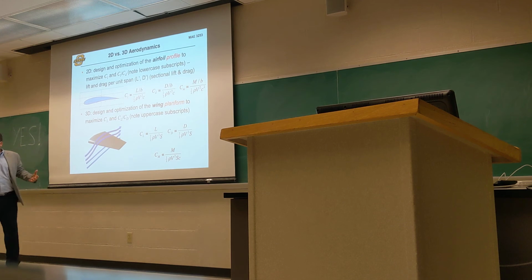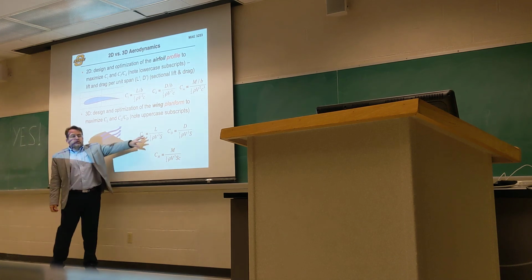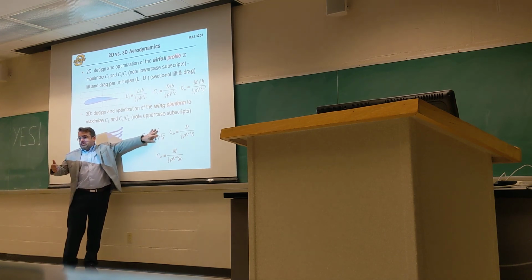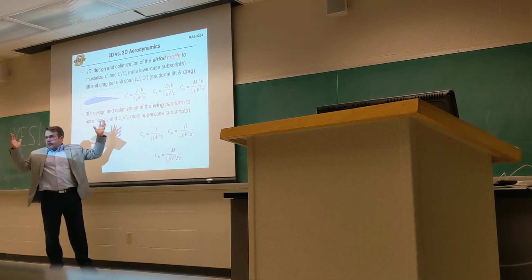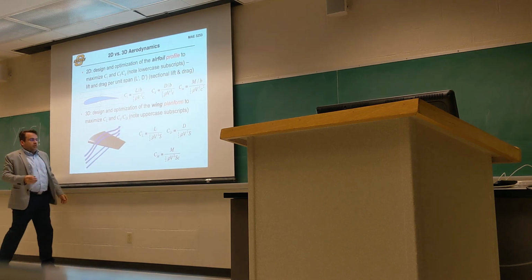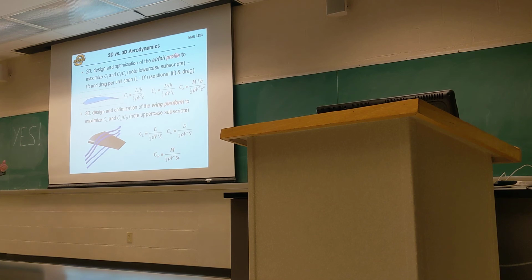And why do we non-dimensionalize them? So that when we're sticking these in a wind tunnel, we only have to do the test once, at a given Reynolds number, a given Mach number. Once I have it for that given geometry, I'm done. I don't have to come back and redo that test if I scale my wing up or down, as long as I'm matching my other dimensionless parameters on which these depend.